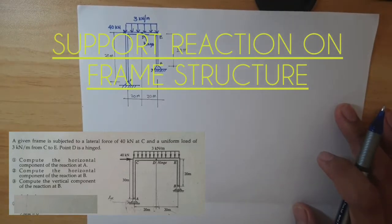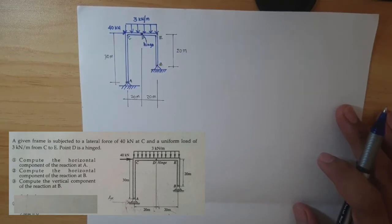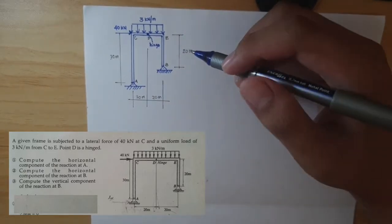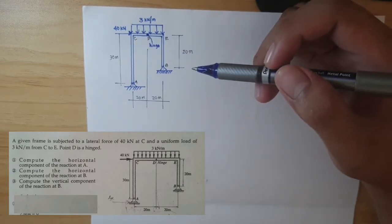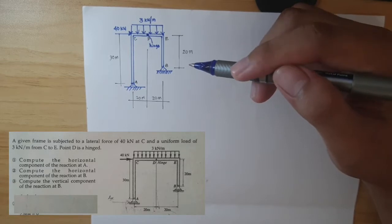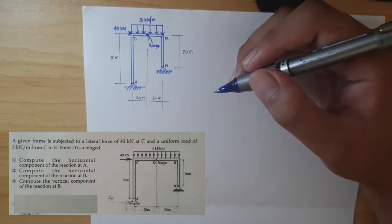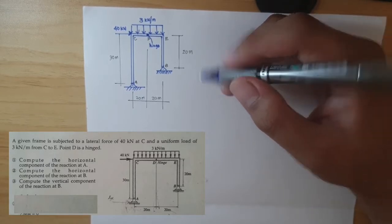A given frame is subjected to a lateral force of 40 kN at C and a uniform load of 3 kN per meter from C to E. Point D is a hinge. Number 1, compute the horizontal component of the reaction at A. Number 2, compute the horizontal component of the reaction at B. Number 3, compute the vertical component of the reaction at B.